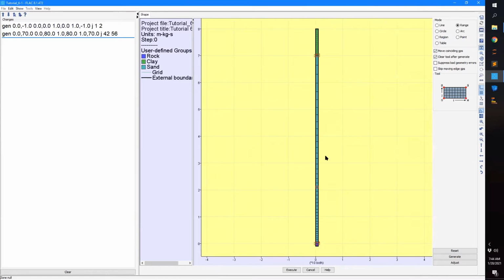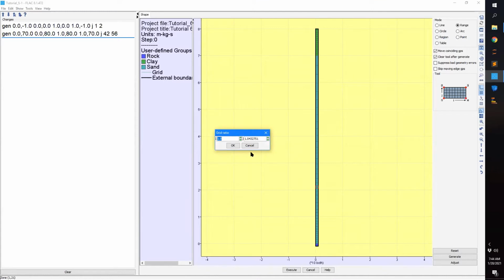height. The way that we adjust the relative changes in the element thicknesses, or in this case height, is with this center node, the center point. So I'm going to right click on the center point. Currently, all of those element heights are getting multiplied by 1.04327 as we go above, which is why they're getting thicker. So instead of doing that, I'm just going to convert that to 1.